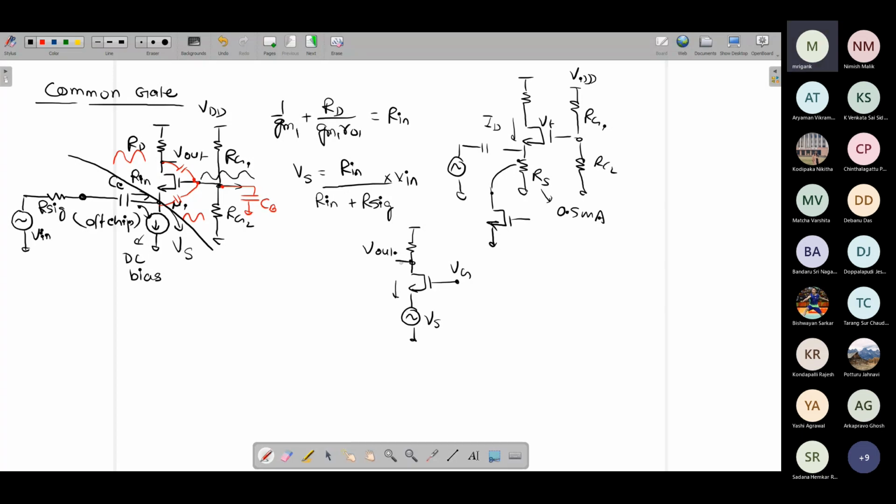It is directly going to be gm VGS. As a result, you get the gm VGS current flowing through the resistor RD, which gives you the gain, equal to gm times RD. And here the polarity is positive, because if VS increases, VGS reduces, the current in RD will reduce, and therefore the output voltage will go up. So even without small signal analysis, this is a non-inverting amplifier, and you get a plus sign.